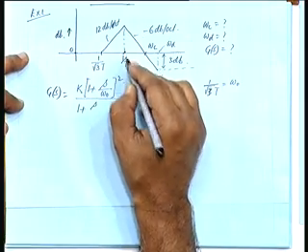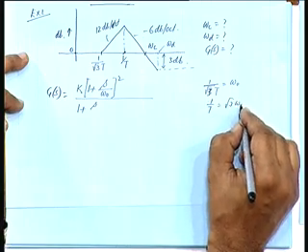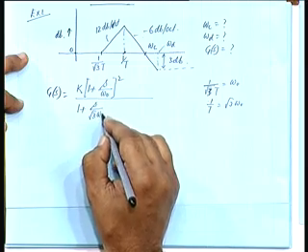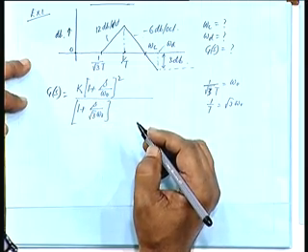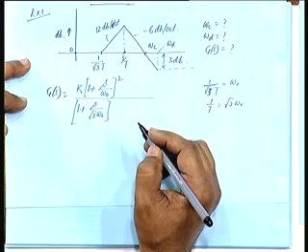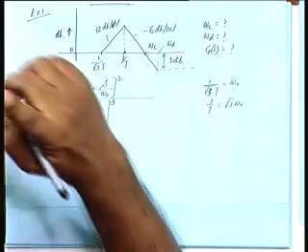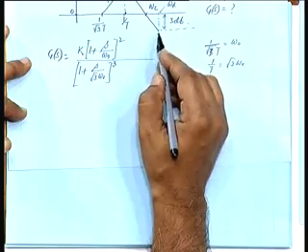So, if I call this 1 by t is equal to root 3 omega 0, so s by root 3 omega 0, then any other answer? Squared, cubed. So, it was going up by 12 dB and it is falling by 6 dB. So, it will be 3 times 6 dB. So, cubed.